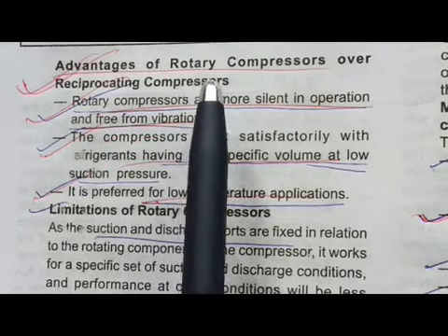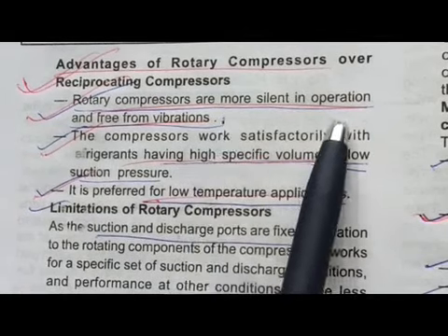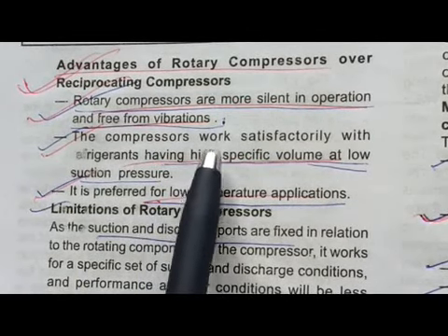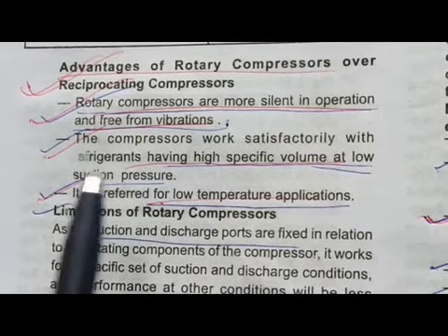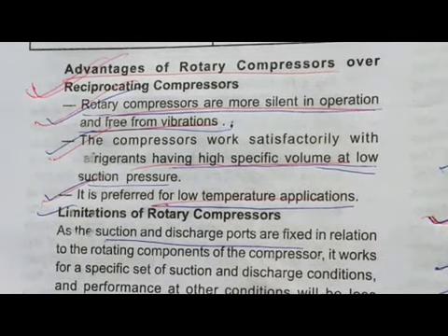These are the advantages of a rotary compressor over a reciprocating compressor. Rotary compressors are more silent in operation and free from vibration. The compressor works satisfactorily with refrigerants having high specific volume at low suction pressure. It is preferred for low temperature applications.